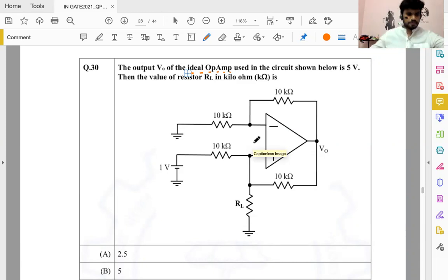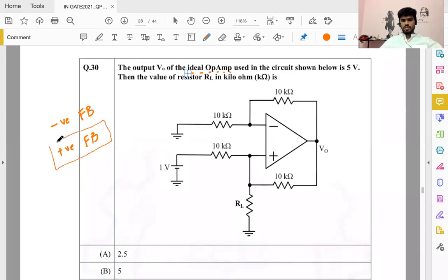First we have negative feedback and positive feedback, right? So is the positive feedback dominant? In that case, our OpAmp rules will not work. But if the negative feedback is such that things are matching, you can still apply the OpAmp rules. And here, which rule will not apply? Let's be clear, this virtual shorting will not apply if this is dominant.